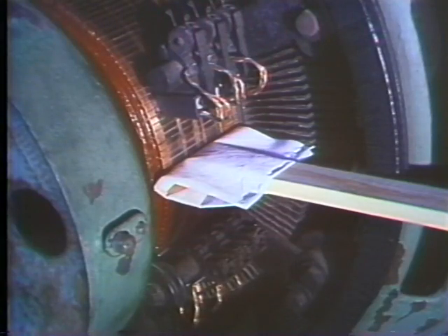You can use a canvas wiper to do the job. It's just a piece of canvas fixed to a wooden handle. The canvas is sturdy enough to clean the surface without removing the film. Don't neglect this area between the commutator segments. It's likely to collect carbon dust, brush chips, copper flakes, and other particles.